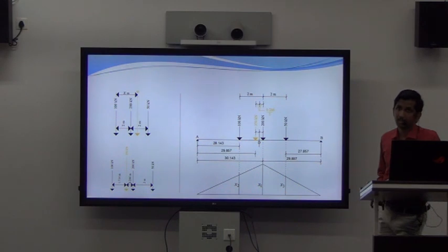In this case, we need to calculate the absolute maximum bending moment. So basically we have to draw the influence line diagram corresponding to bending moment at which point, and again please note, as per the condition, absolute maximum bending moment will occur under the critical load, and in this case critical load was the load near to our resultant, and in this particular problem it is 200 kilonewton.